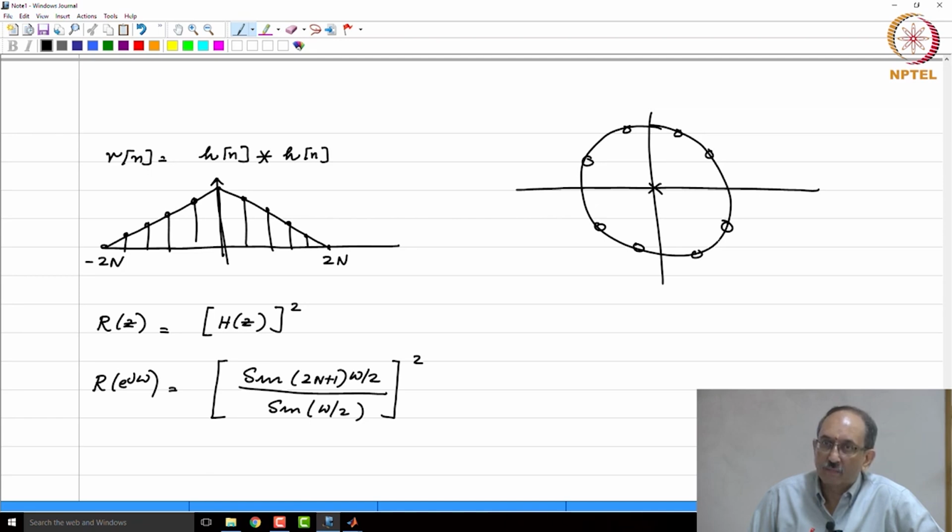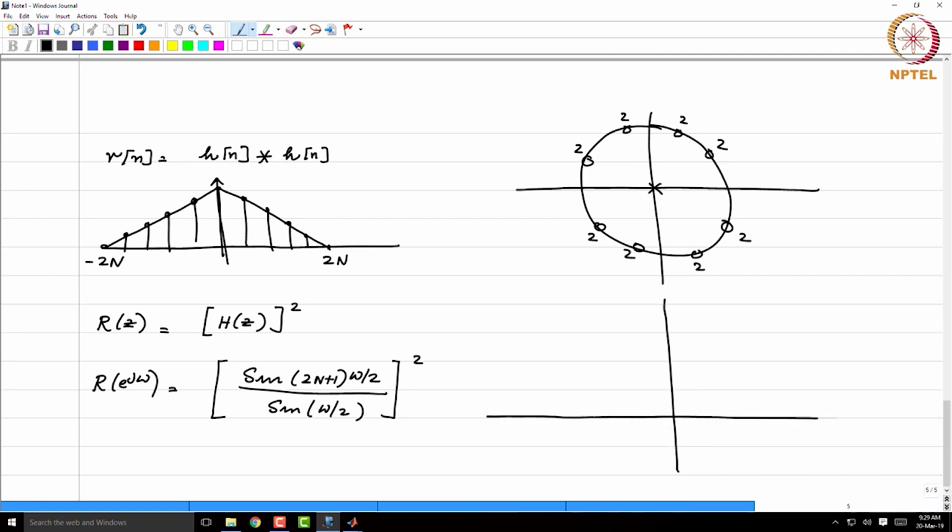So, they will be second order, repeated zeros, that is right. So now, rather than simple zeros, you now have double zeros. Now, let us see what this means. In terms of frequency response, here at omega equal to 0 you have a certain value, and then as you approach the first 0 on the unit circle for positive omega, the response drops